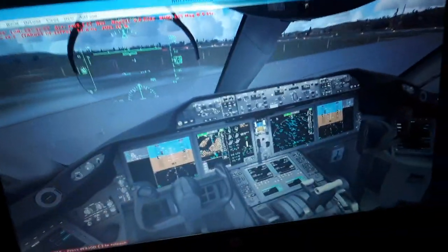So we have also the localizer crossbars, the flight director crossbars for manual guidance of the aircraft, and the autopilot crossbars for automatic guidance of the aircraft. We have also the angle of attack of the aircraft as it flies in the flight mode, and later with the autopilot and the autothrottle in vertical navigation mode. We have also the HSI with the magnetic heading and track.